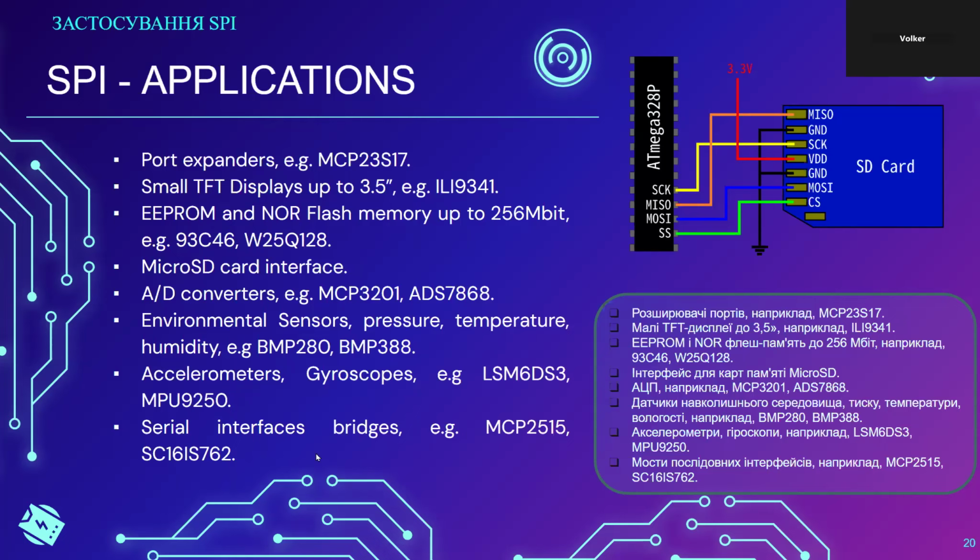You can do that because, for example, the maximum speed of a traditional CAN interface is a megabit per second, but the maximum speed of an SPI interface can be 10 megabits per second. So there's plenty of time for the SPI interface to get the data that's arriving at the CAN chip, at the MCP2515.